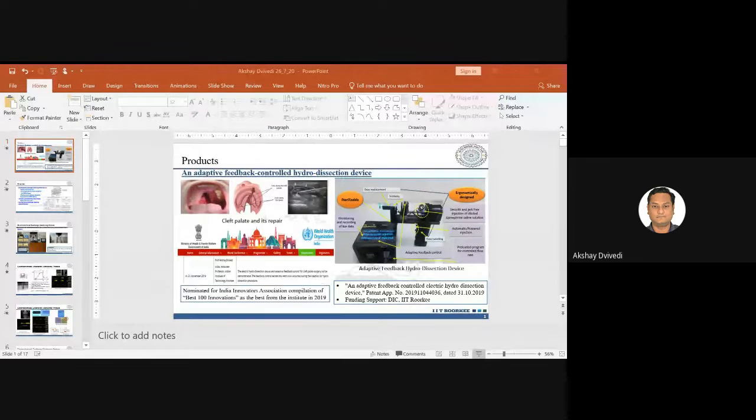Why do you want to make this particular film thin? It was realized that if the film thickness is too much, and in fact this is what the customer desires, they want this film to be as thin as possible. The reason is, whenever you have sparks, those sparks should be high frequency sparks. This implies more sparks in less time, and those sparks should be sufficient to create a temperature so that your work material can actually melt.